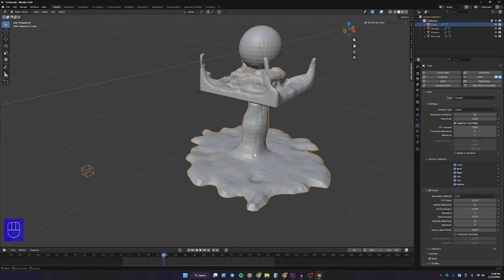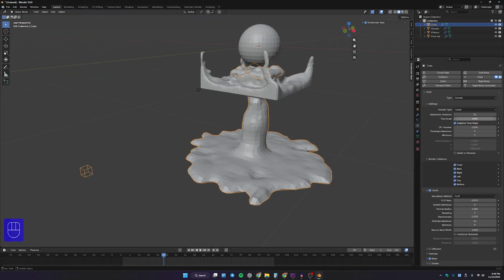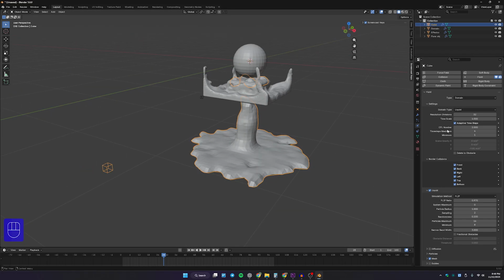But if I select the domain and go here into the physics properties, under the resolution division, we have the same 32 resolution divisions for the smaller one and also for the larger one. So the resolution division is by default the same, but since the resolution division is small for the large one, it has to increase the pixel size to fit this resolution division.